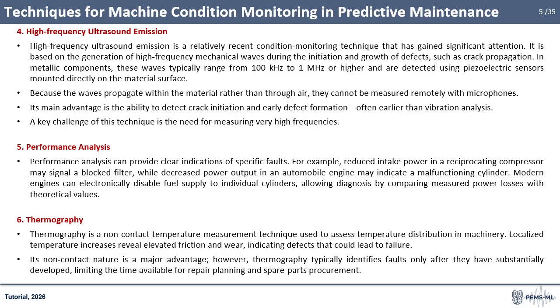Performance analysis is another diagnostic approach that can provide clear indications of specific faults. For example, reduced intake power in a reciprocating compressor may indicate a blocked filter, while reduced power output in an automobile engine may point to a malfunctioning cylinder.